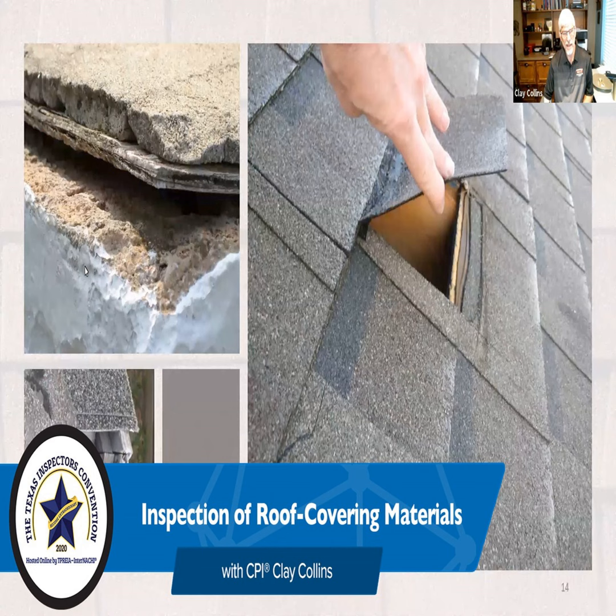Is anybody going to fix that? Probably not. But I would definitely encourage you to document that the shingles aren't flat there, and that it appears to be related to decking more than it's related to the installation of the roof cover. But also note that that can create a problem with the roof cover itself. And remember that it's unlikely that the manufacturer would warrant any damage caused by that improper installation.